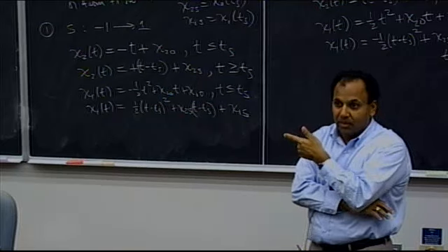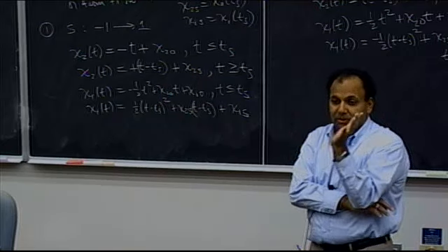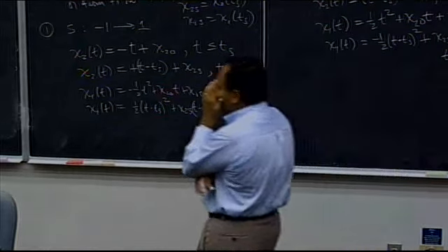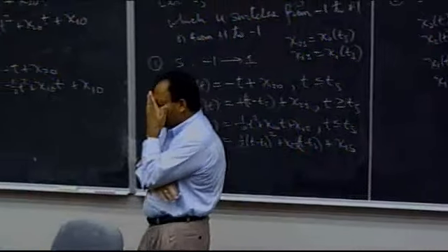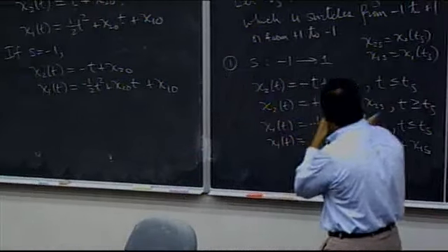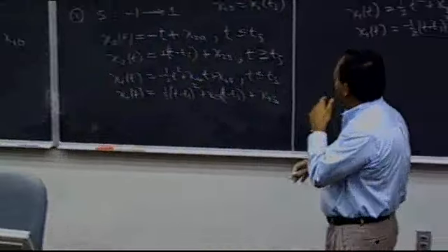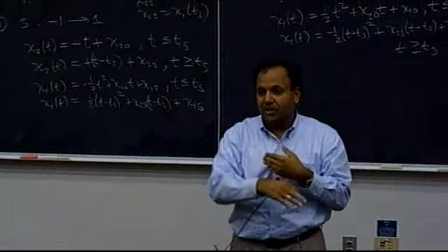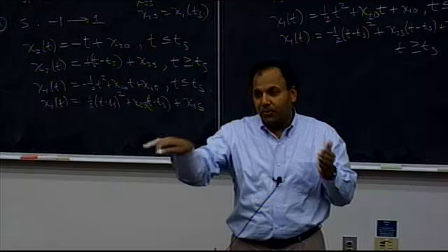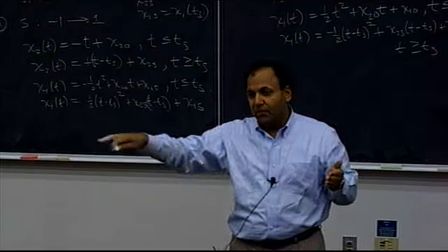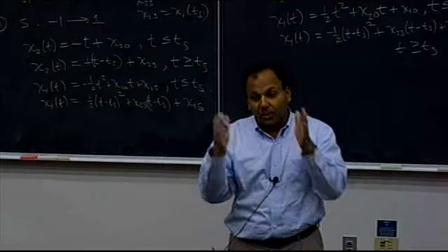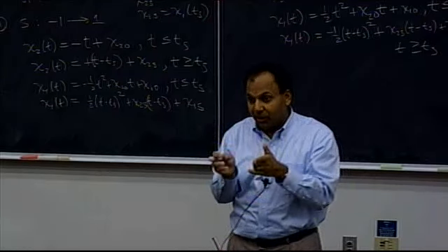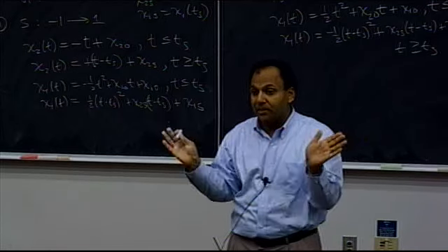And this is just for a double integrator that you get this. For other kinds of problems, I'm going to talk about in a few weeks. I'm going to talk about problems for which, remember I mentioned to you that the conditions for the costate and the optimal control were that the optimal control was +1 if the costate's negative and vice versa. And I said that we had to rule out the possibility that you could have an arc where the costate was 0. Well, there are some problems for which that does actually appear, where you get an arc where the costate's actually 0, and you cannot determine the control.